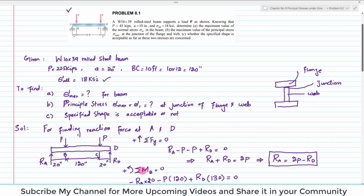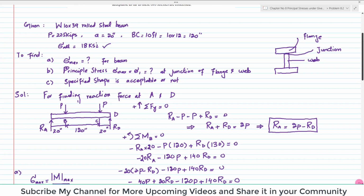Now we can apply the second condition of equilibrium, that the sum of all moments about point B is equal to 0. You can take the summation of moments at any point equal to 0, A, B, C or D. I have taken it at point B. When you apply this condition, at point B the force RA is producing a moment about point B, and the moment will be RA into 20.